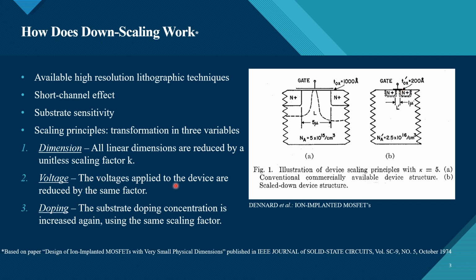The voltages applied to the device are also reduced by the same factor. And the third is doping. The substrate doping concentration is increased, again using the same scaling factor.